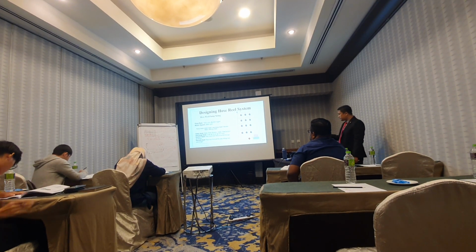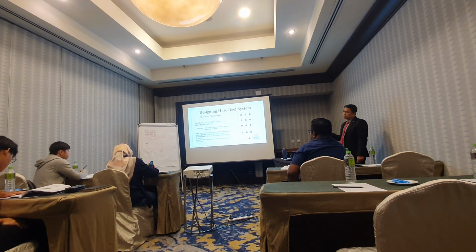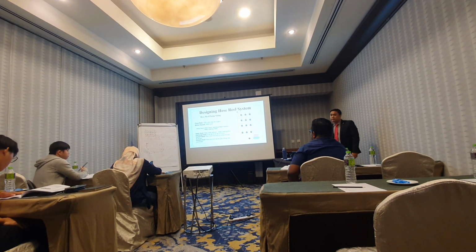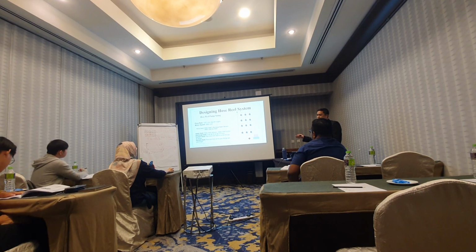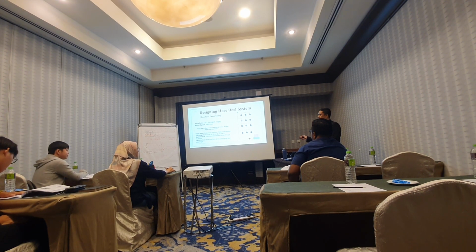If the pipe length is 100 meters, you need to cater for 100 meters of losses. That is the calculation of the pump. Normally this is done by the mechanical engineer, who can calculate this pump easily. Do you understand? You can calculate it, right? You studied it.